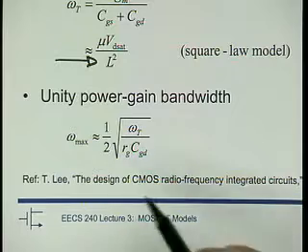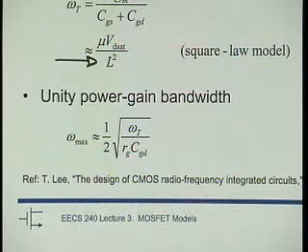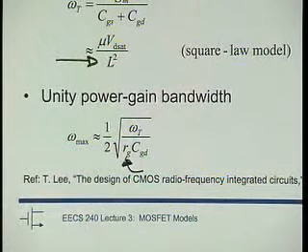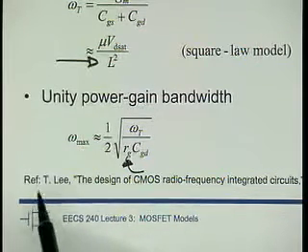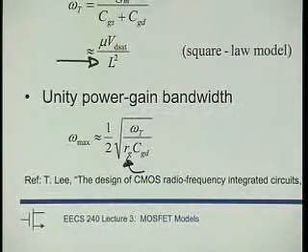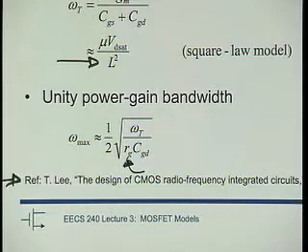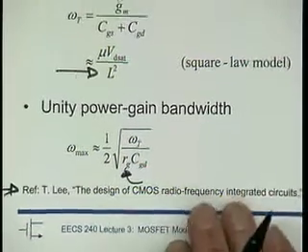This expression captures that. It's a little more complicated because it includes the gate resistance: if we make the gate material resistive, the signal never really reaches the gate of the transistor, and we will have lots of dissipation there. If you're interested, this figure of merit is used more often at high frequency. This is a reference that has a nice and simple discussion of that.